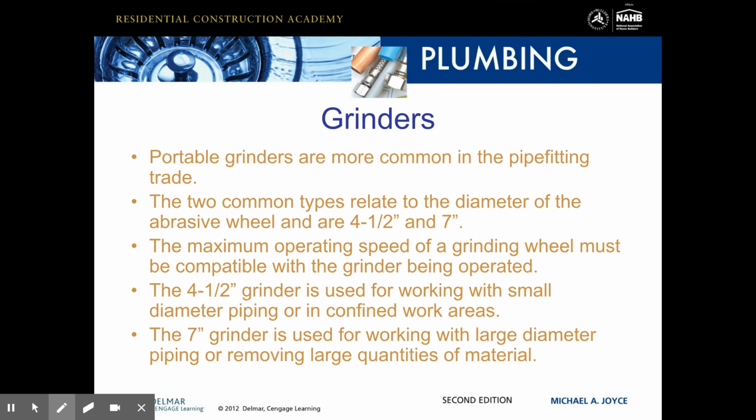You don't want a grinder that's able to spin faster than what your grinding wheel can take. If you do that, there is a chance that your grinding wheel will blow apart and cause injury.